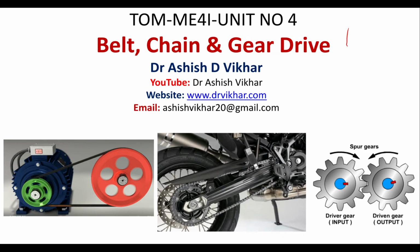So let us start to understand first what is meant by belt, chain and gear drive. As you can see in this picture, the first picture is of belt drive, the second picture is of chain drive and the third picture is of gear drive. In the first picture, you will see that one belt is mounted on two different pulleys. The small pulley is mounted on the shaft of the electric motor and the big pulley is mounted on another shaft where we want to transmit the power.